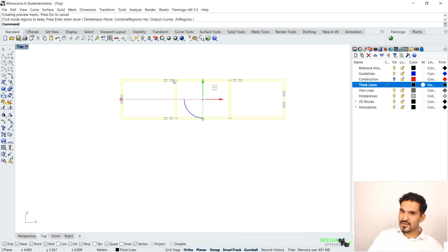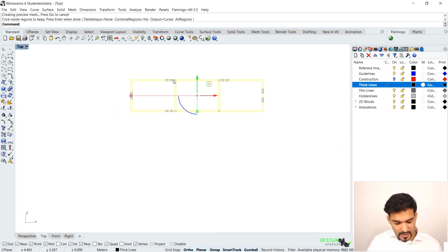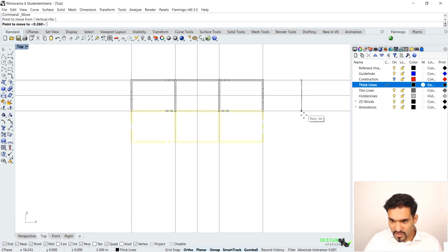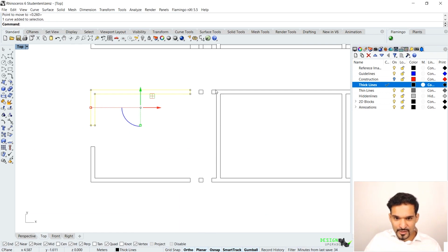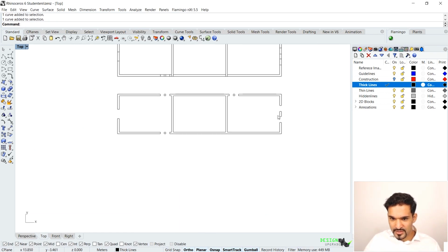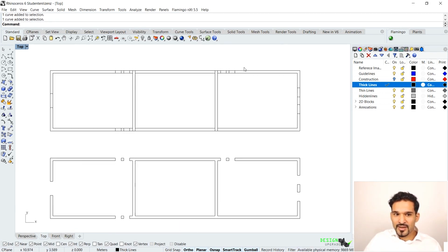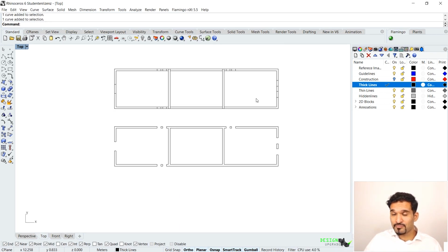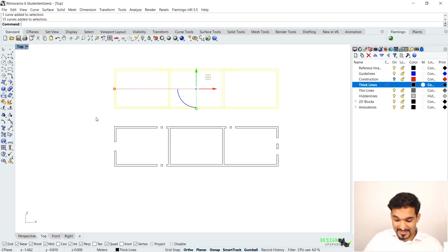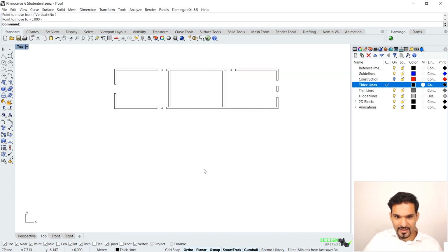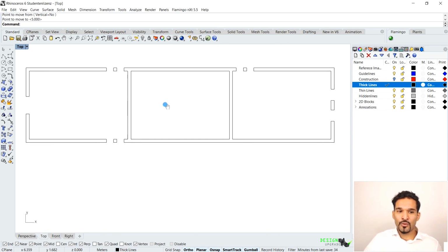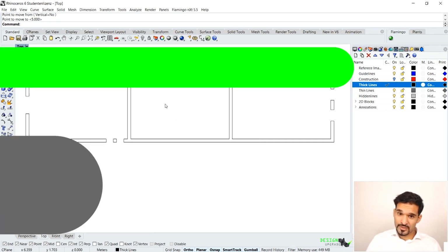Now they are still selected. What we could do now is either lock it because I want to delete some stuff, or we could just move it away. So maybe I move it down, let's say 5 meters, and I have now my new clean closed wall geometry, as you can see here. And here I have my line work that I've been doing before. Now we can simply take that, delete it, and put this guy back up 5 meters, and I have now created my clean wall types using the CurveBoolean.